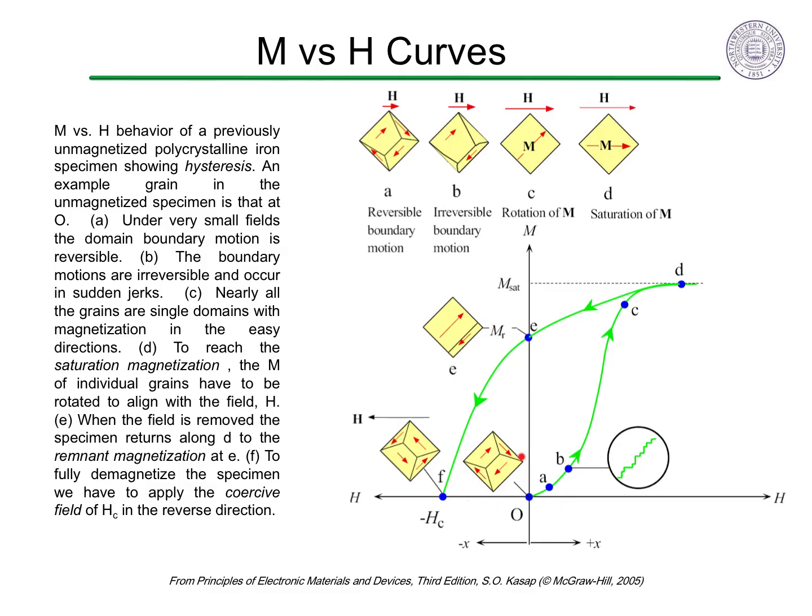When a demagnetized sample is placed in a magnetic field, the magnetization increases first by domain motion. Some domain motion is unhindered and easily reversed. Some occurs in jumps because of domain pinning, which makes it less reversible. The domains magnetize along the easy direction first. After the grains become single domain, further magnetization along the field direction requires the magnetization to rotate out of the easy direction. When the magnetocrystalline anisotropy energy is overcome, the saturation magnetization is reached.